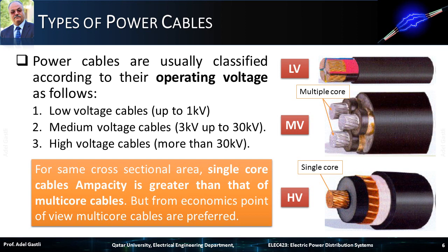Thus you would find that for small conductor installations, 3-core cables were used, and for large conductor installations single-core cables were used. But from an economics point of view, multi-core cables are preferred. Thus, for low current short length requirements, for instance in industry, 3-core cables are better, whereas for high power circuits, for instance in transmission, single-core installations are more cost-effective.